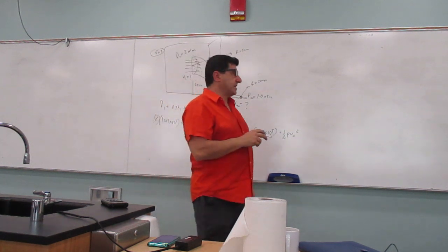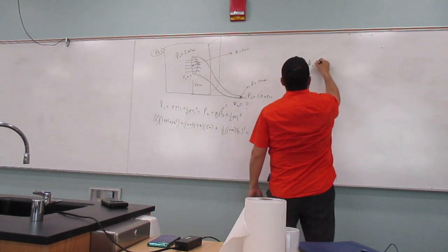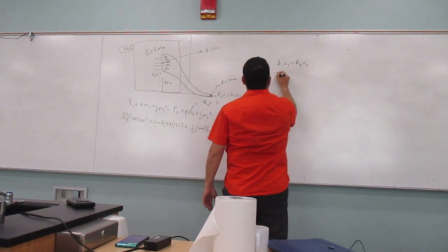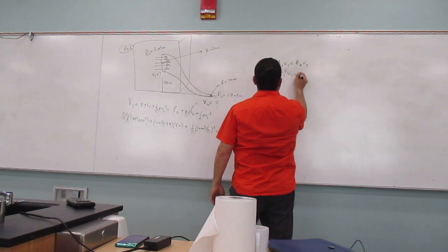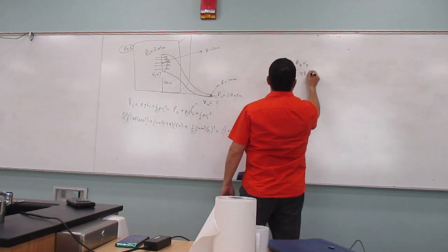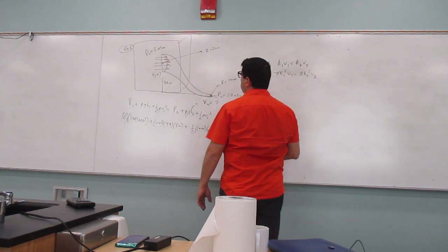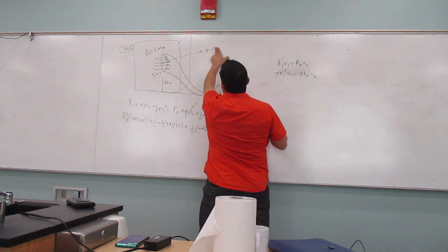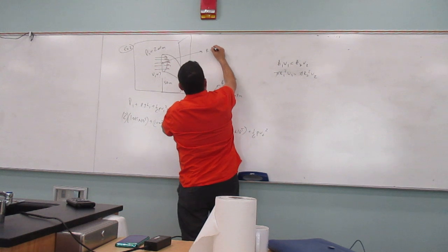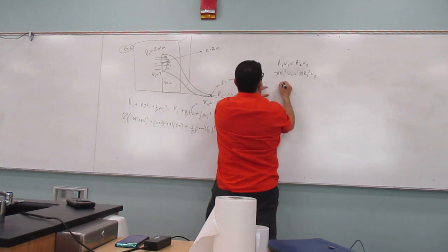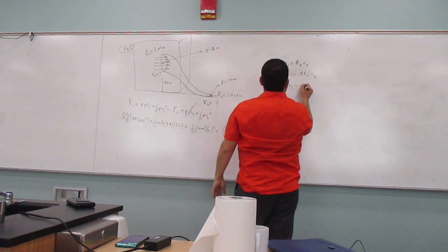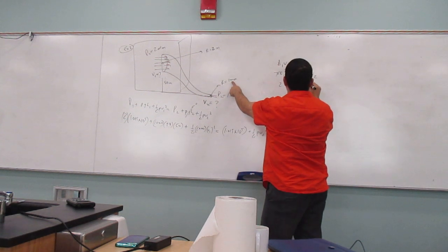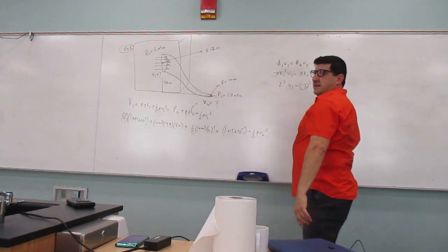But the volume flow rate conservation says what? A1 V1 is equal to A2 V2. So now pi times R1 squared, pi cancels. What was this? 2 meters radius. And then this one was 20 centimeters, so 0.2 meters. You see?